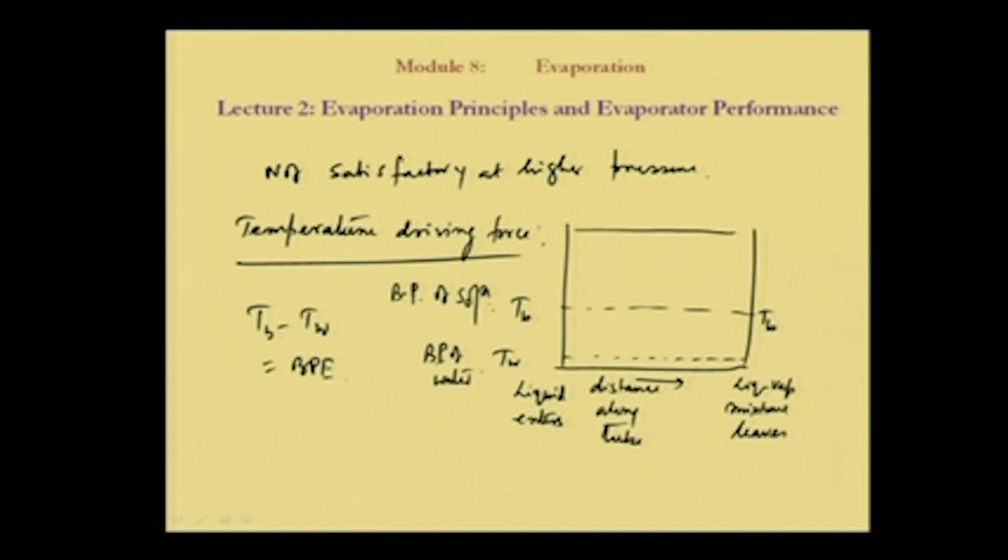Here, this is the saturation temperature, and it is coming with some higher temperature and is coming down. So, this is Ts. Now, this is the vapor and this is the liquid. So, this region is for superheated vapor, and this is for subcooling.